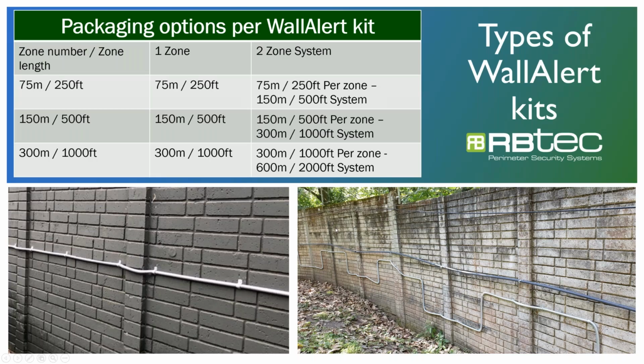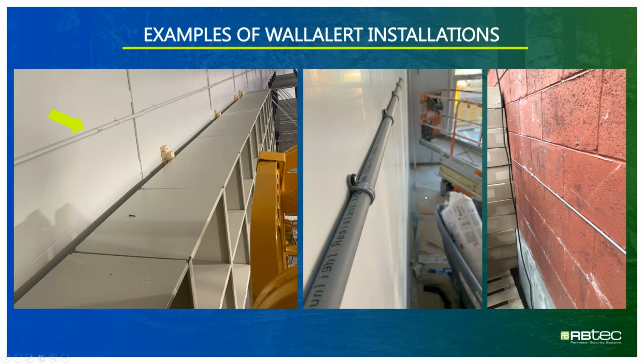Meaning that if someone has an interior wall for a warehouse, for a secured building, for a vault, for something that they need to have vibration sensors that are more than a couple of feet, and instead of those point vibration sensors, the small vibration sensors that some companies sell, this is a continuous vibration sensor that we attach to the wall and usually installed in some kind of a pipe or a conduit, and that will detect drilling, hammering, any impact to the wall to try to get to the other side of the wall.